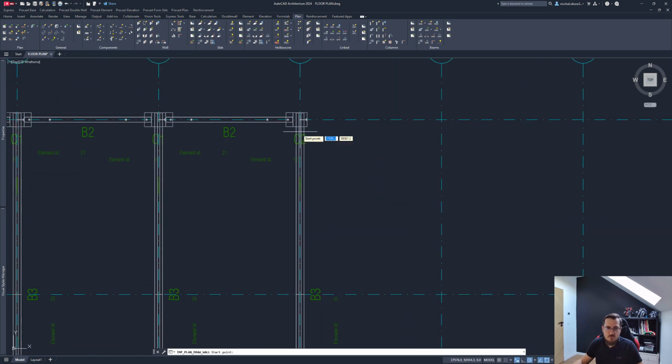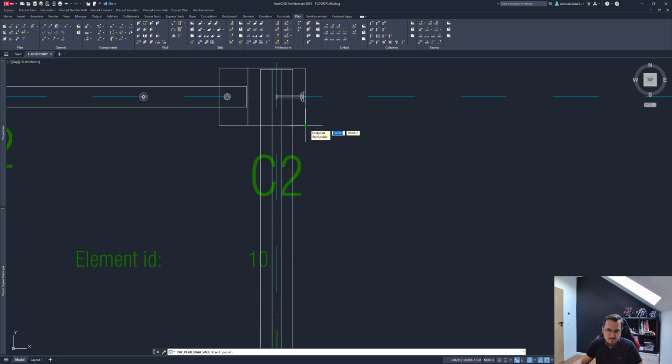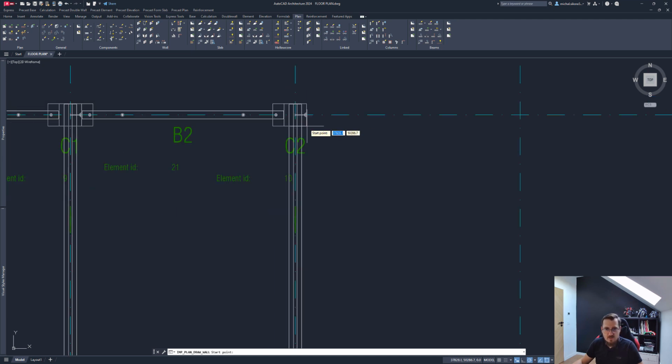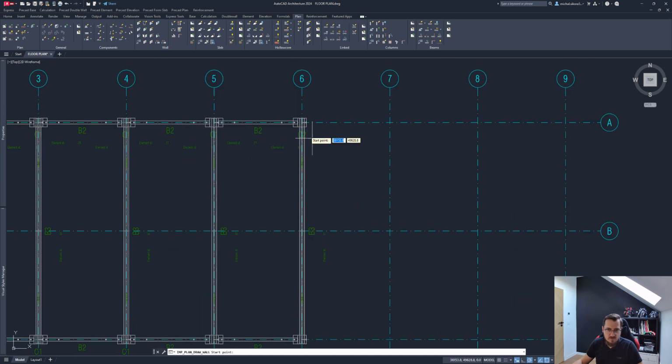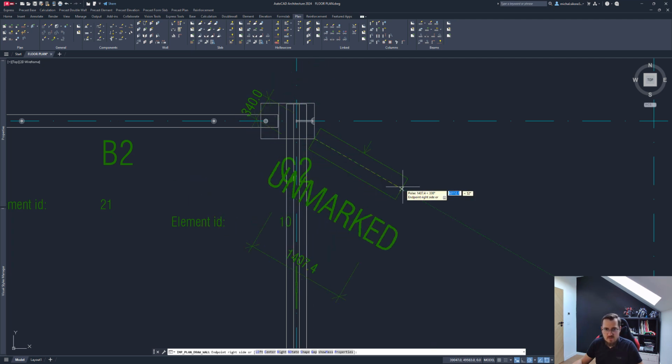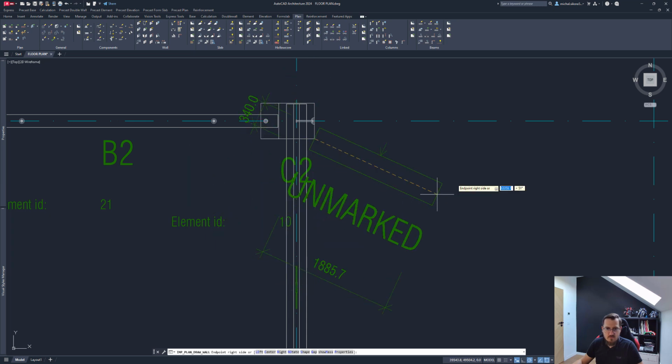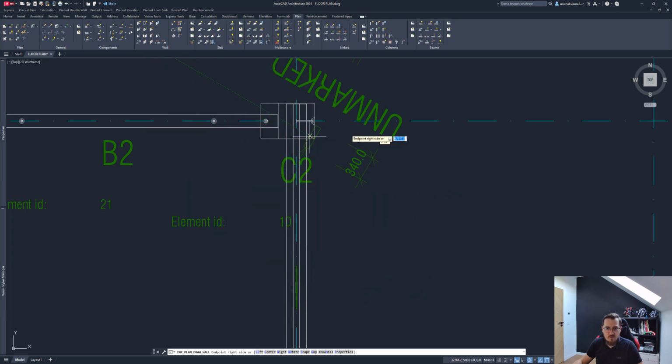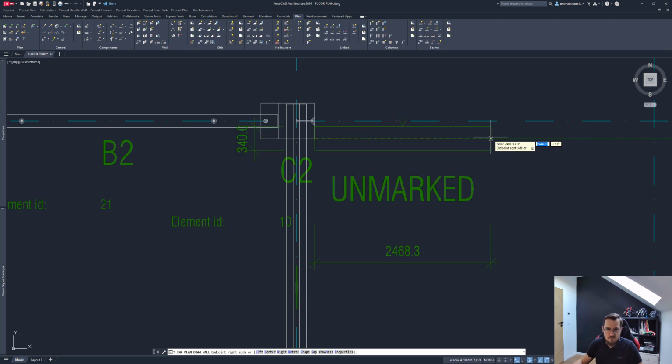Okay, so first I would like to place sandwich panels from this corner of the column to the other side, and I'll do it like so. I'll snap to one point. An important thing of note is first the direction we draw in. As you may see, if I go to the right, there's an arrow on the top of the wall as we look at it, opposite to the unmarked text that you can see, right? This basically marks where the internal panel is for our sandwich panels, right?